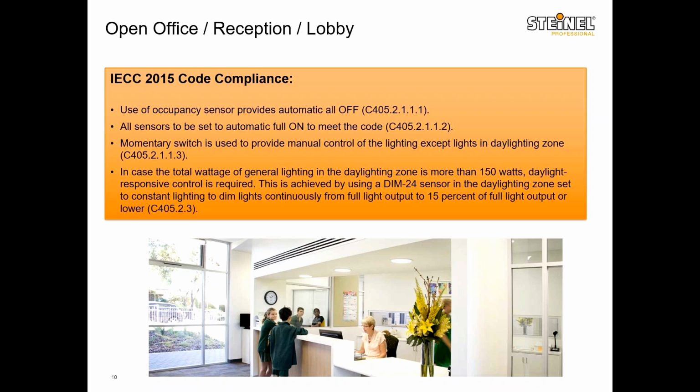I don't think the reception area of a self-storage center would ever fall into a daylighting zone or a daylight harvesting application. But then again, if it meets those requirements and falls under those applications, then you need to have daylight responsive controls in that area.